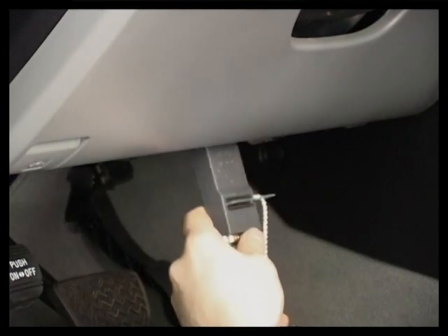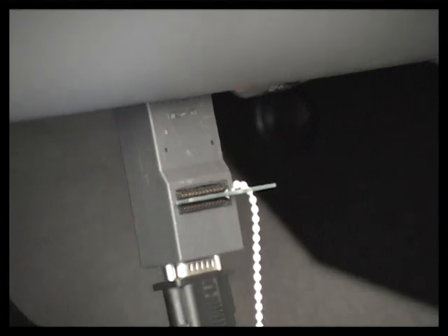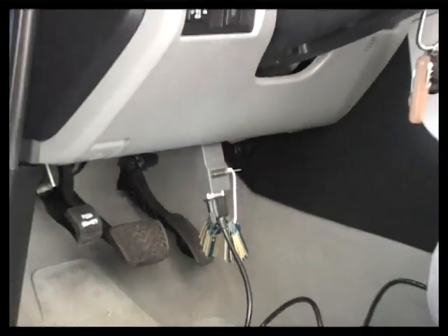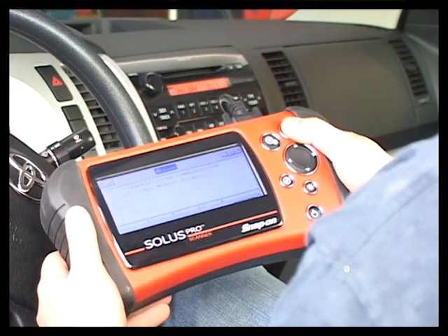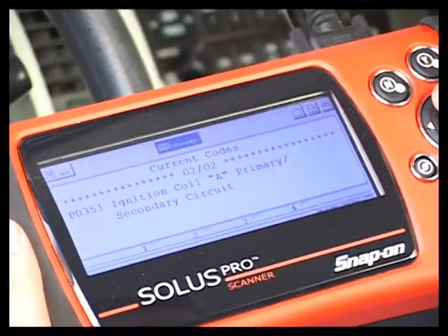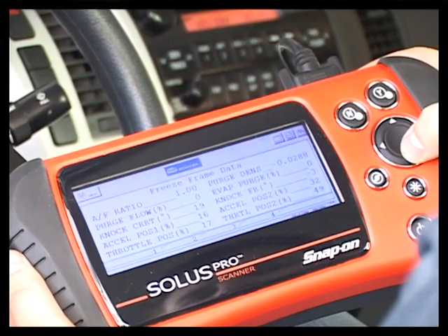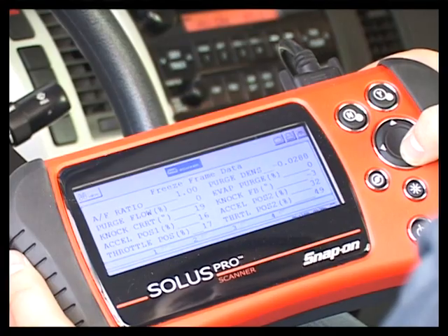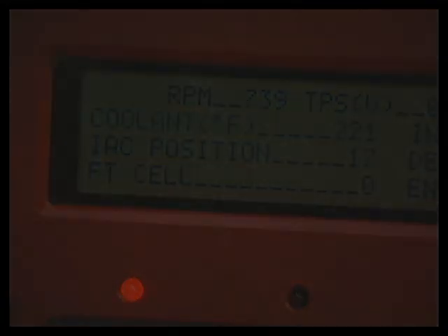With late model vehicles, a scan tool is connected to the vehicle's diagnostic connector. The scan tool then communicates with the vehicle's onboard computer to retrieve trouble codes, display circuit electrical values, run tests, and give helpful hints for finding difficult problem sources. This can all be done quickly and easily without disconnecting wires or removing parts.